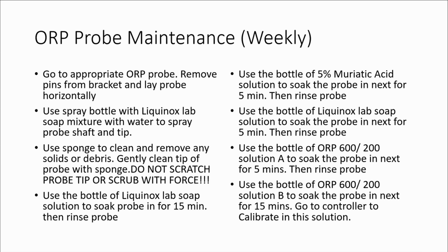So, just a question: when you put it in hand and hold that same dosing rate, you can see what the ORP output is. Then when you put the probe in, you're able to see what the probe is reading now, to see if there's something weird, if you damaged it or... Yeah, I'm trying to remember exactly what happened. Because our ORP at the chlorine contact chamber runs between 500 and 600 millivolts is what the reading is. It's in millivolts.